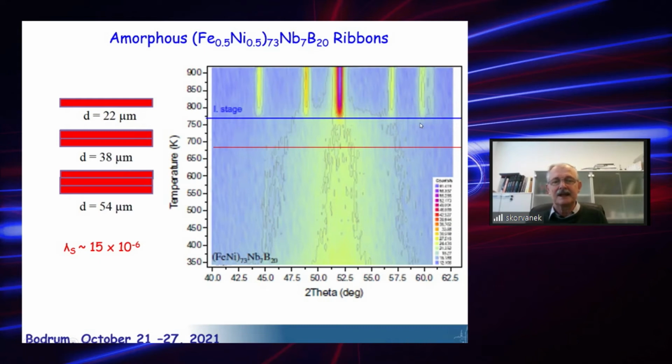We did here also annealing after preparation to make some kind of stress-release annealing in order to improve magnetic softness, because in this case of material the main factor is the magneto-elastic anisotropy, and when we decrease stresses, then this factor is somehow diminished.